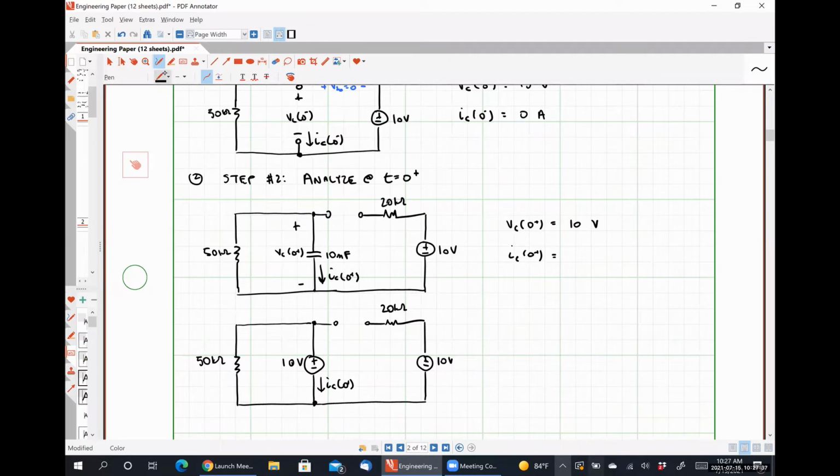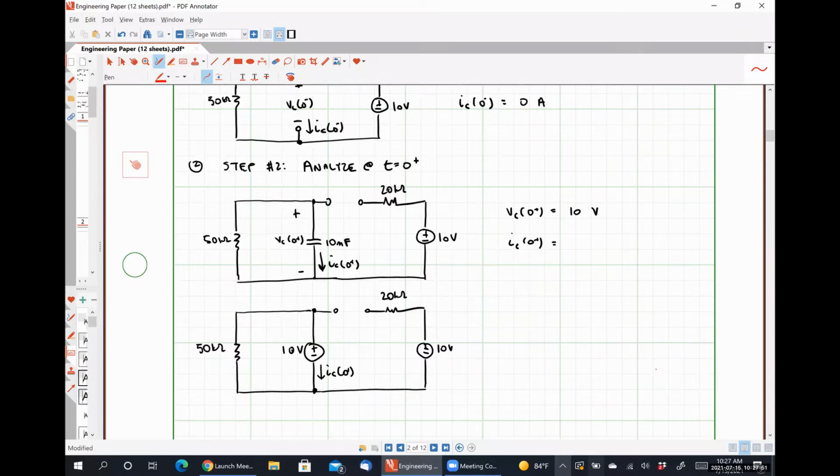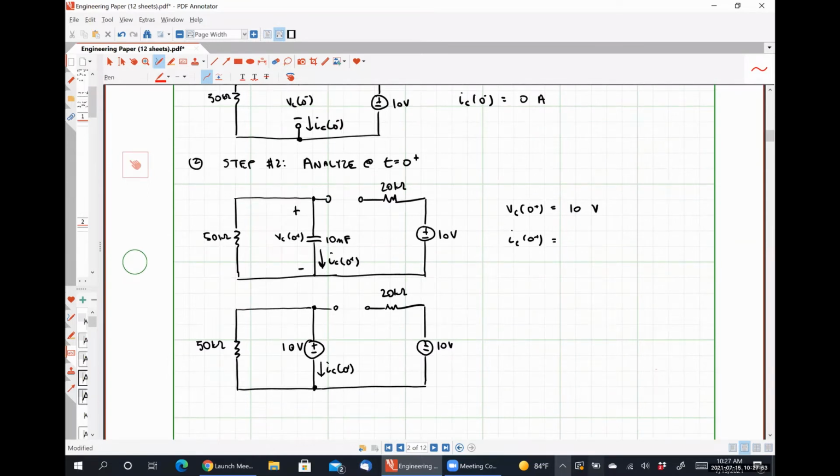Could you just analyze that left hand of the circuit using like KCL? Or you could probably do voltage division to find the voltage across that 50 kilo ohm. Is voltage division necessary? I would argue no, it's all in parallel, so wouldn't it just be 10 volts?